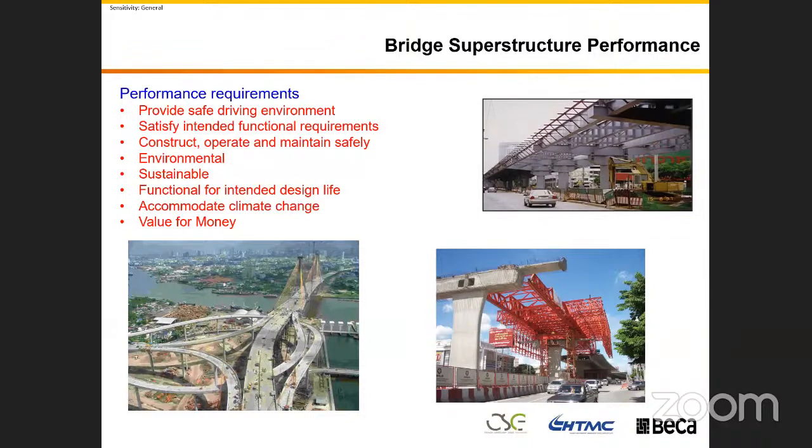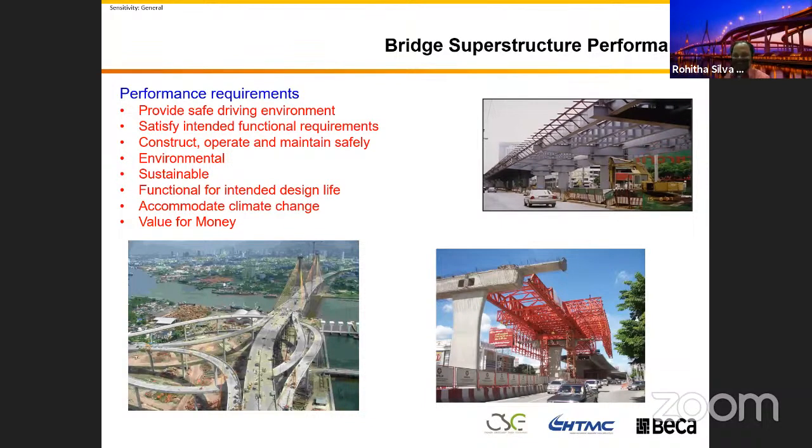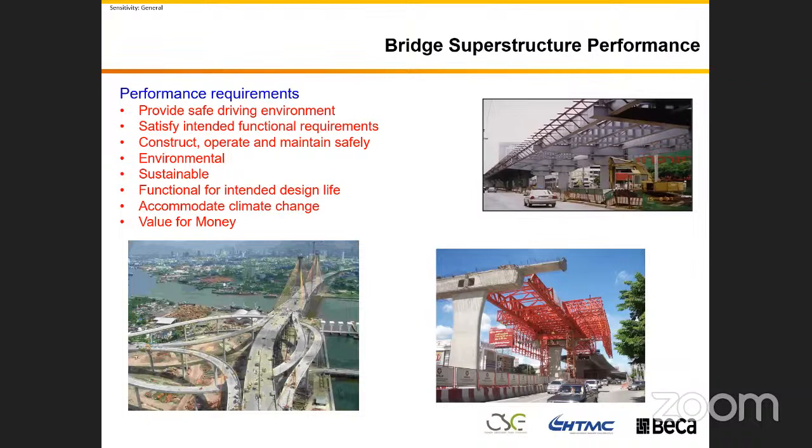Yeah, Ravindra. Another thing is the surfacing on top of the bridge. We always get questions on these things, and today you explained that it's very difficult to get the tolerances on the surface of the bridge. That's exactly right. I never thought about that, but yep. And we find it's very difficult to keep the surfacing because it's always subjected to various stress reversals.